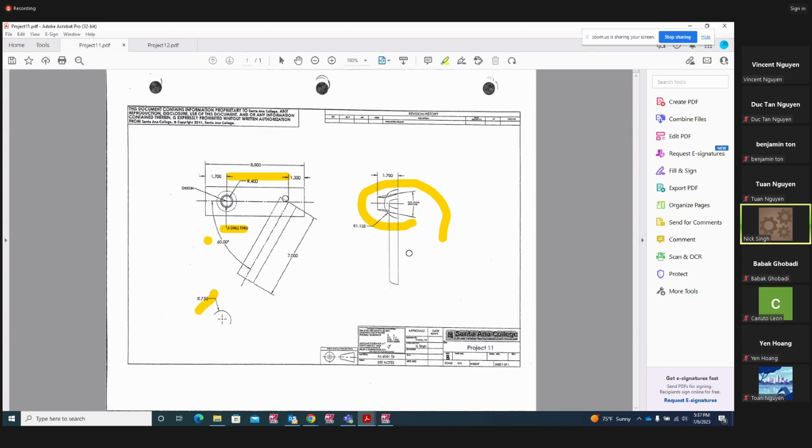We have a surface coming with radius 400 circle, and right underneath you see in hidden lines right here, it's a surface in a cone shape, and the draft angle is 20.02 degrees. So first we can create a surface on that, and this is how this works. Let me show you that.